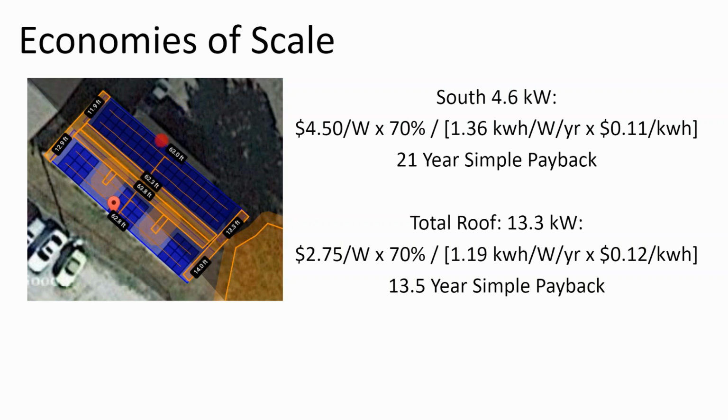So in this example, there's this tree on the side of the building, and after a thorough shade analysis, we actually determined that this array right here got shaded as much as the north side of the rooftop, and the best design would be to stick the array further away from the tree. So that shouldn't be surprising there. But then it's like, okay, well, this is just one tree. So the client can chop the tree down, proceed with the array as built.